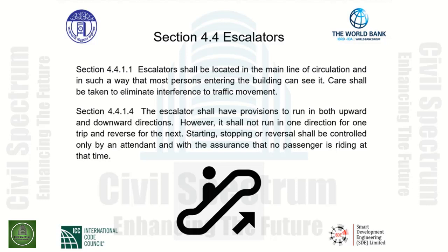Starting, stopping, or reversal shall be controlled only by an attendant, and with the assurance that no passenger is riding at that time. This is a safety precaution, and if the escalator will run in a different direction, it must be controlled by an attendant.